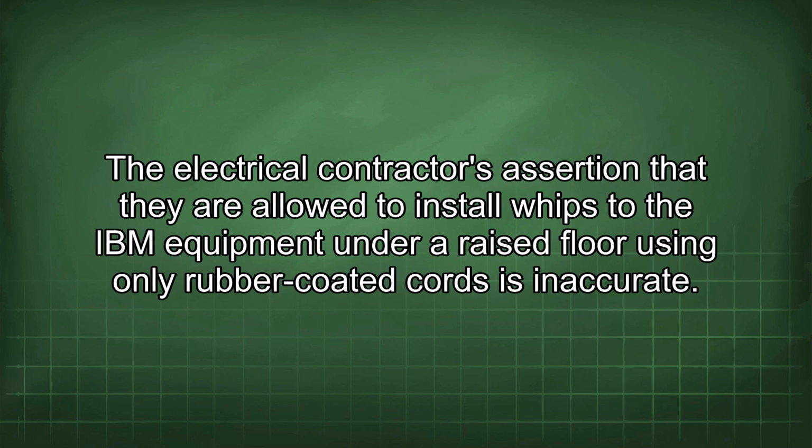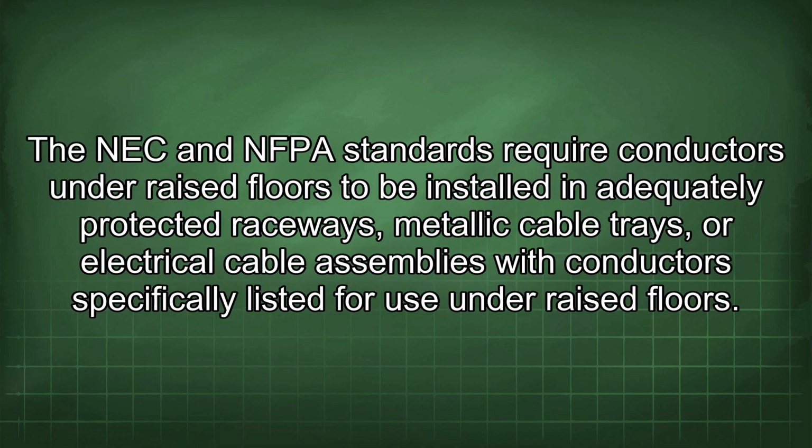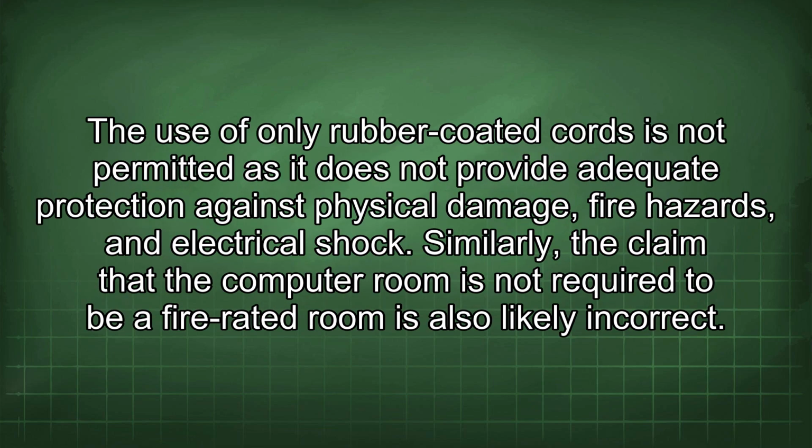The electrical contractor's assertion that they are allowed to install whips to the IBM equipment under a raised floor using only rubber-coated cords is inaccurate. The NEC and NFPA standards require conductors under raised floors to be installed in adequately protected raceways, metallic cable trays, or electrical cable assemblies with conductors specifically listed for use under raised floors. The use of only rubber-coated cords is not permitted as it does not provide adequate protection against physical damage, fire hazards, and electrical shock.